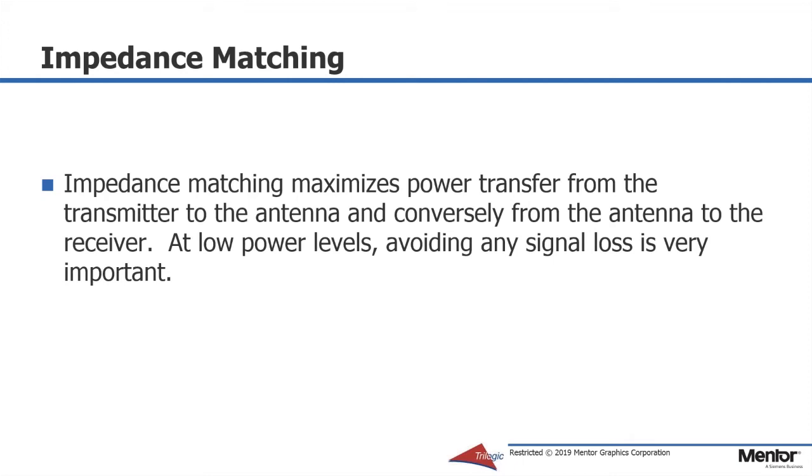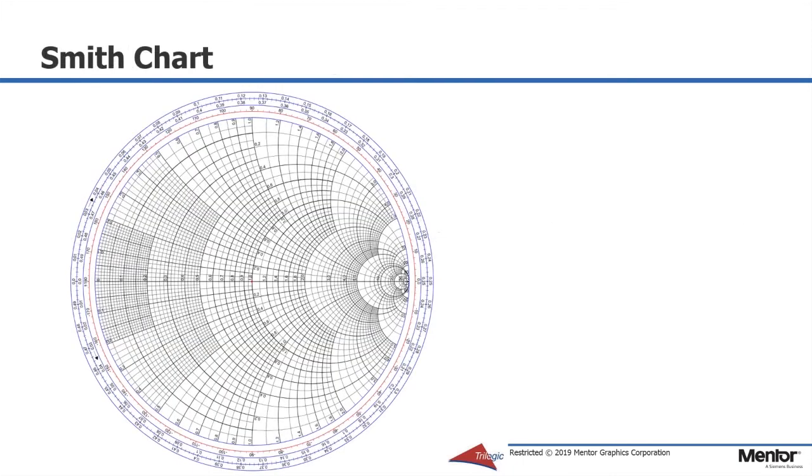So we have to pay very close mind to how we connect our radio to our antenna. Now, this is something that scares a lot of developers. Impedance matching is not an uncommon source of consternation for those unfamiliar with how it's done or the tools commonly used. And this is a Smith chart.